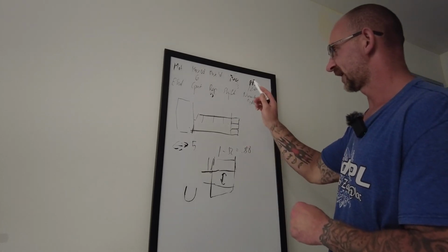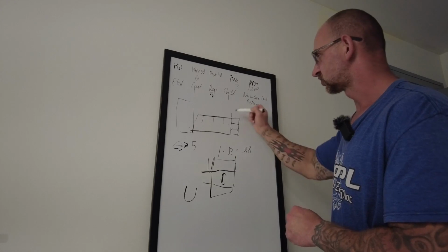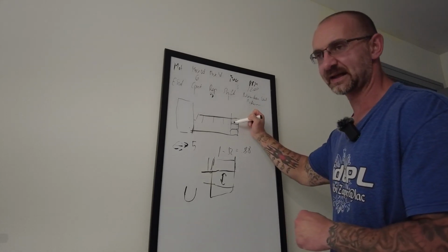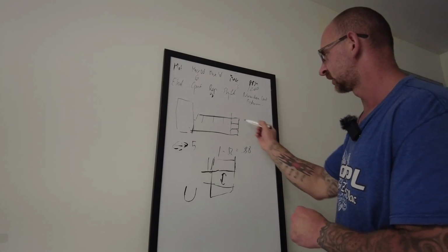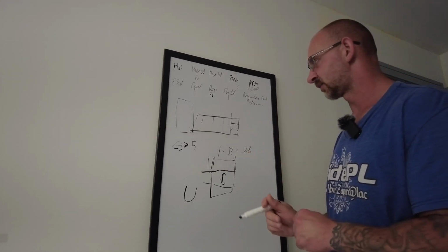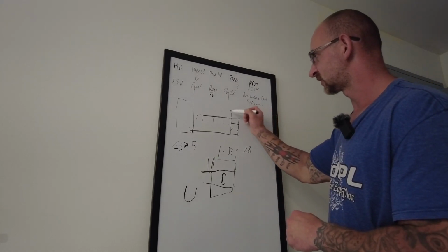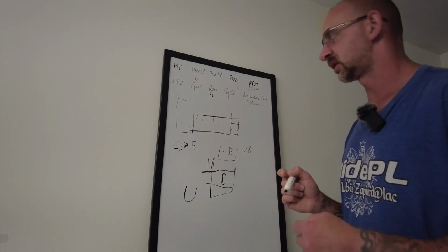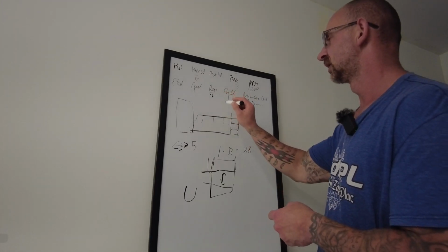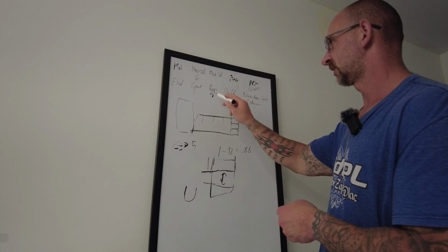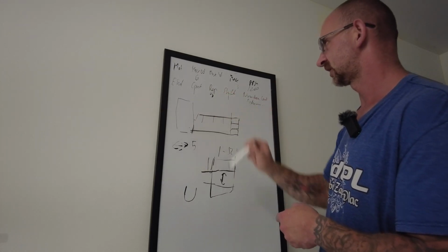Then it's going to retract. Then you have the shift of the turret to start and repeat. But since I have an M0 there, it's going to wait for me to press the start. So I'm going to come in and hit this part with the hammer, grab the part, and then press the start, and now it's going to repeat the cycle. So this is one of those things: how do you continue, how much you are repeating, and how much it is going to shift.